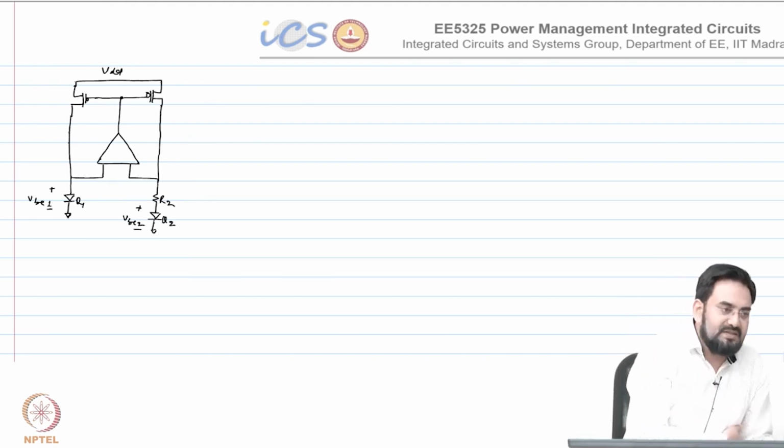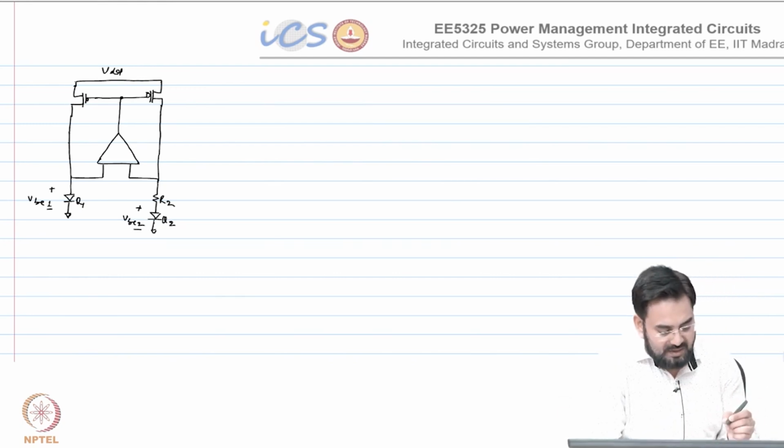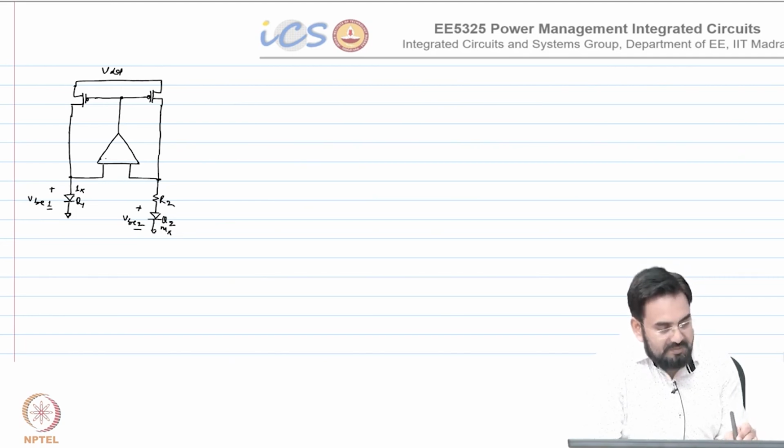So, now your resistor is replaced with your MOSFET, and I talked about this yesterday. You can use either resistor or this current, and most of the time we use these current sources. So, now if this is 1x device and this is, let us say, mx device, what will be the sign of this? Positive. This is positive? No, that is negative. This should be negative, because there is one inversion in the PMOS.